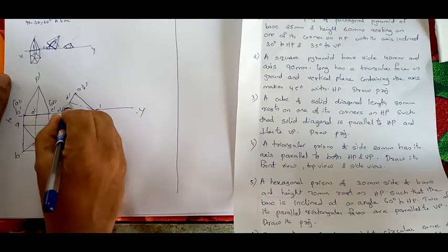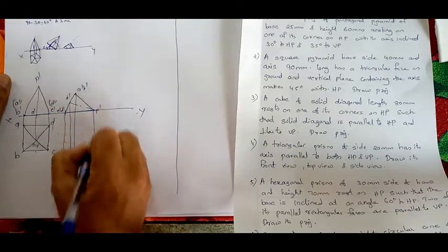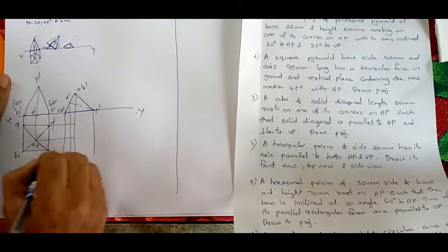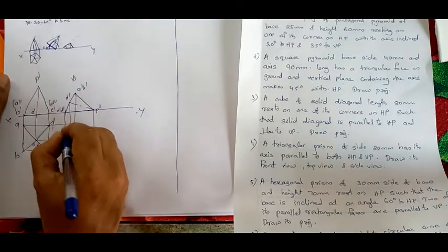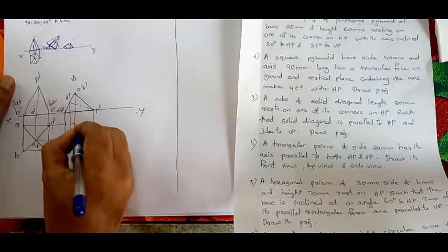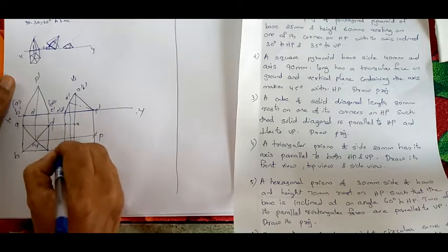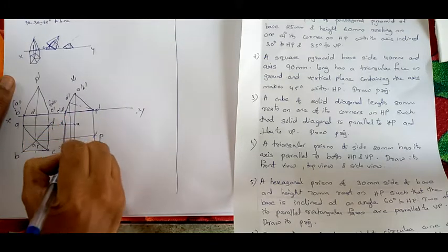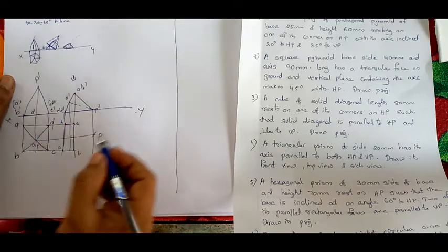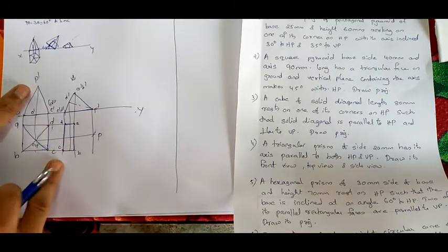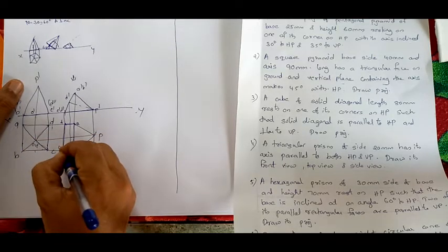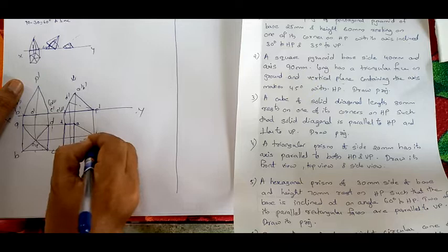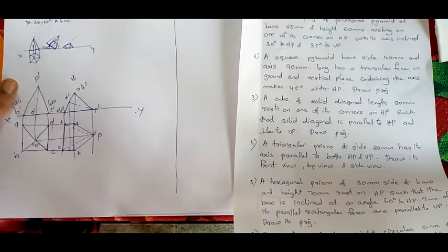If you project it, this will be P. So from the top you can see the base. A, B is reverted, right? A is here, B is here, C is here, D is here, the square is fully visible. So regarding visibility, AP is visible, BP is visible, CP is going inside this square, so it is not visible. DP is also not visible. Here the base is visible, that's why.